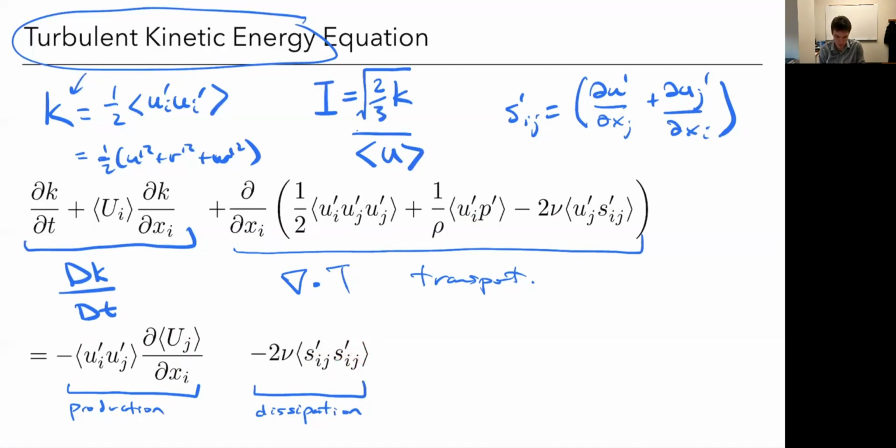This term here is only going to be big at the smallest scales, because remember, these are derivatives, these velocity gradients. So they'll be large at the very tiny scales, where the turbulence is fluctuating very quickly. At the big scales, this term is negligible, but as I zoom into those smaller scales, this term becomes big and it's always negative. So this is where energy is lost. So this basically tells me about how turbulence works. Again, we call this an energy cascade.